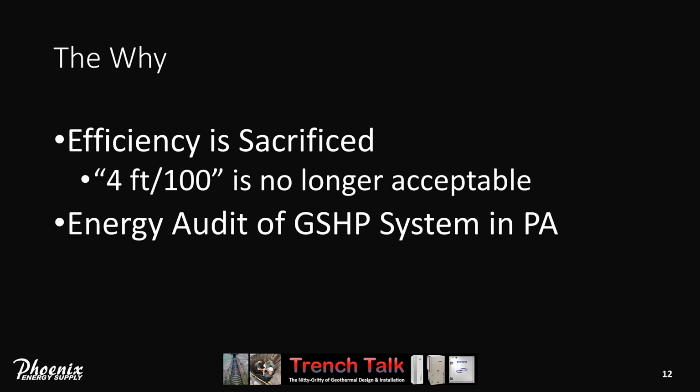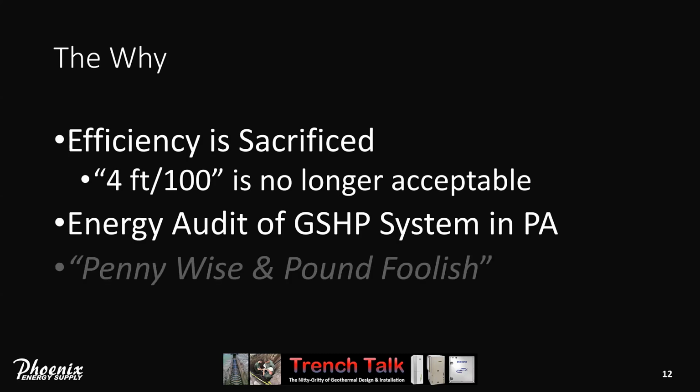And they wondered why their operating costs were so high. So we recommended to go to variable speed, put two-way valves in, and we dropped the energy consumption by about 90%. So to summarize, if we try to save a nickel or two by pipe sizing and making it a little smaller, we're sacrificing the investment that's been made into a geothermal system.